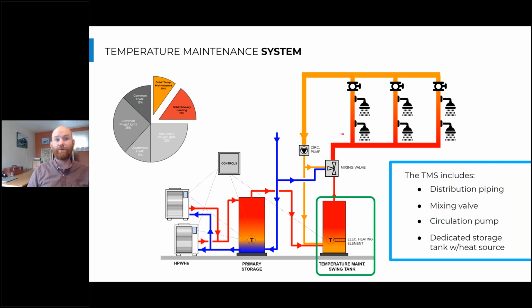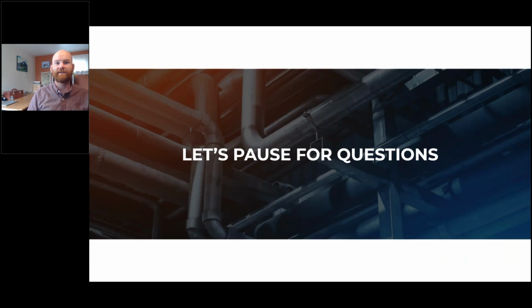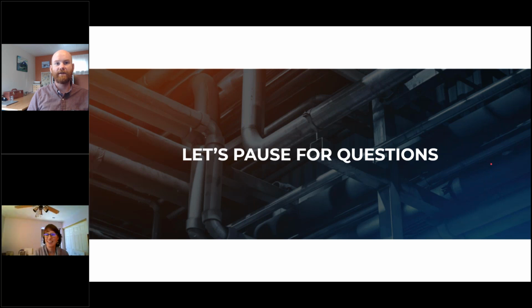If we have a very short distribution system that's super insulated, we're not going to see that level of temperature loss, and we're going to see the circulation pump operating very slowly, or much slower than if we had a large distribution system. So in that case, it's less of the Achilles heel, but it's still something to be aware of when you're designing these systems. But yeah, absolutely great note. It pretty much is the Achilles heel. It definitely was for a lot of the early designs.